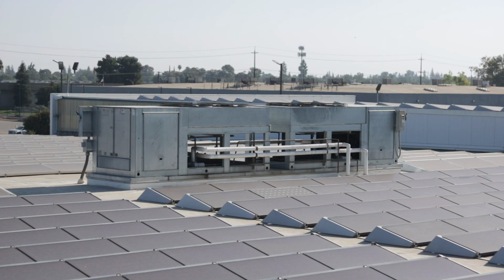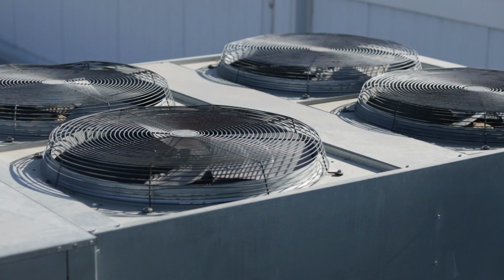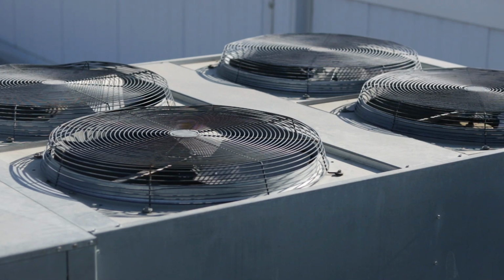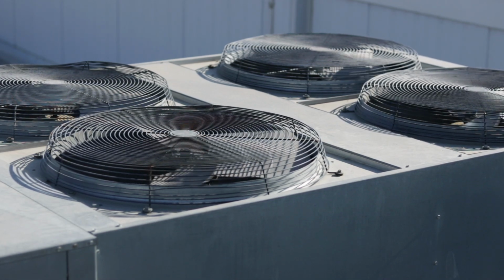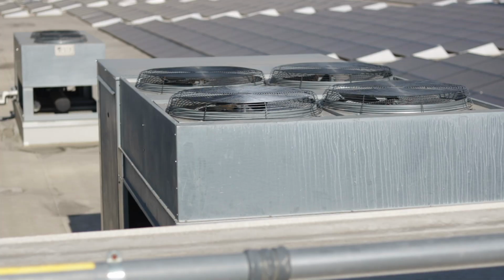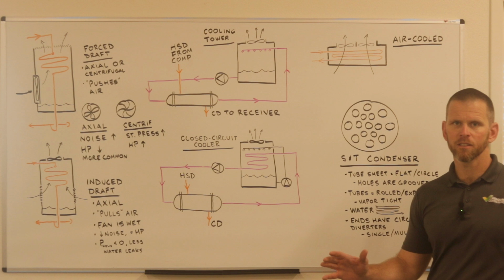To summarize, air-cooled condensers provide a reliable and cost-effective solution for heat rejection in refrigeration systems. Their water-free operation, low maintenance requirements, and versatility make them a popular choice across residential, commercial, and light industrial applications. However, water and evaporatively cooled systems offer higher efficiencies and are more widely used in large industrial systems, especially when ammonia is the refrigerant.